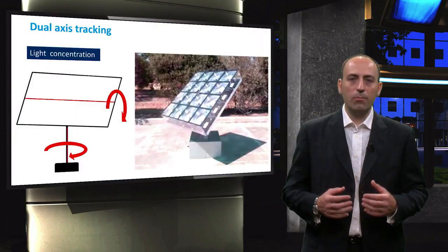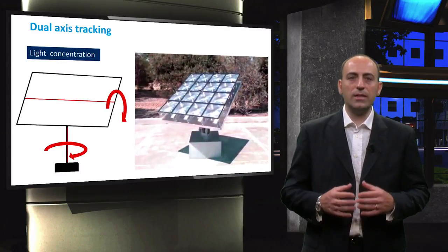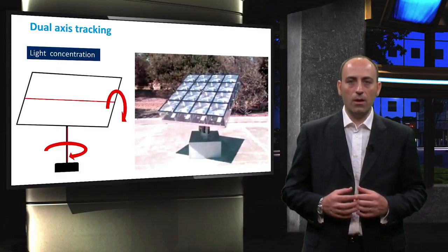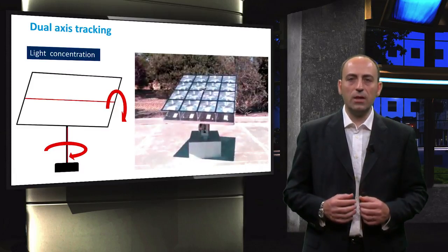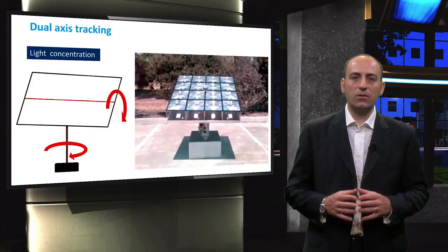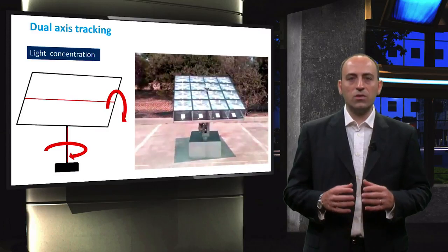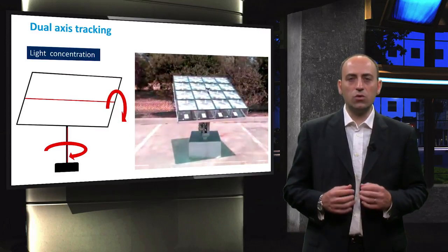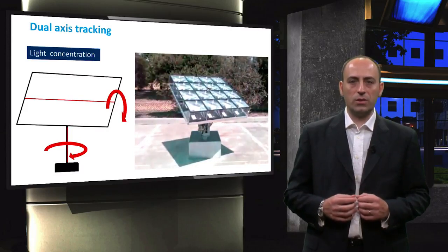Here we have an example of a photovoltaic concentrator system that follows the sun during its daily movement in the sky. You can also see that, contrary to conventional photovoltaic systems, it uses so-called Fresnel lenses that concentrate sunlight to intensities up to and over 1000 suns. The sunlight is concentrated onto small and expensive, highly efficient multi-junction solar cells.